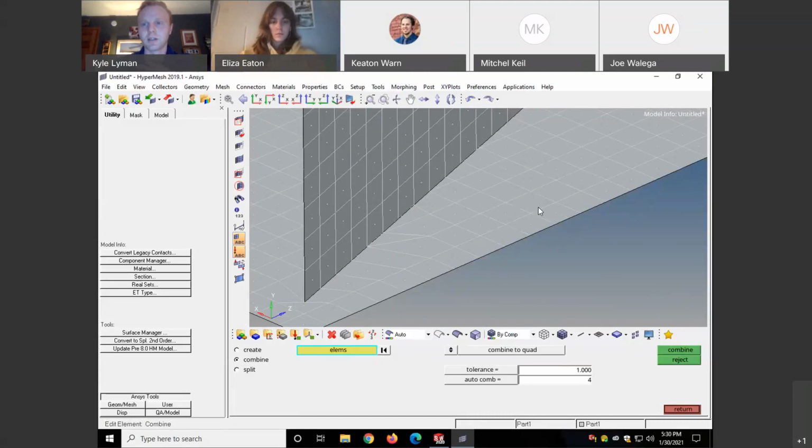Usually, what happens is if you've got relatively low changes in gradient across your mesh, you can use large elements in that region. But when the gradient starts getting really steep, that's when you need to refine the elements so you can capture the actual stress. Right. Okay. That would make sense. Yeah. Thank you for jumping in.